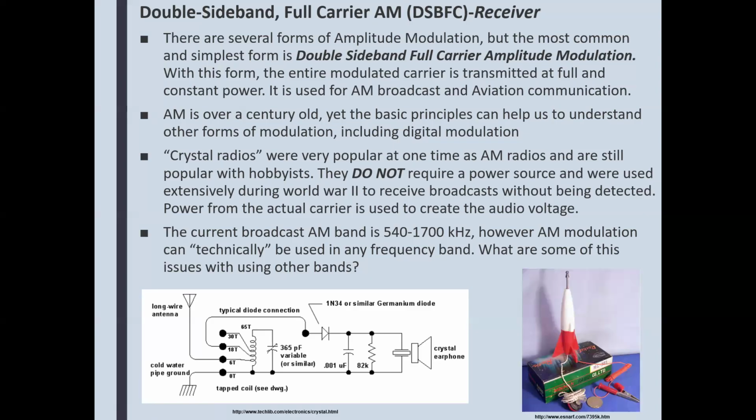The transmitter is transmitting the full carrier double sideband, and the receiver is receiving the upper sideband and the lower sideband, and we only need to have one of the sidebands because the other sideband is almost like a mirror image of the first one. So why do we need to have both? Can we chop one of them off and save the space in the frequency spectrum so we could have more channels? Can we do that?